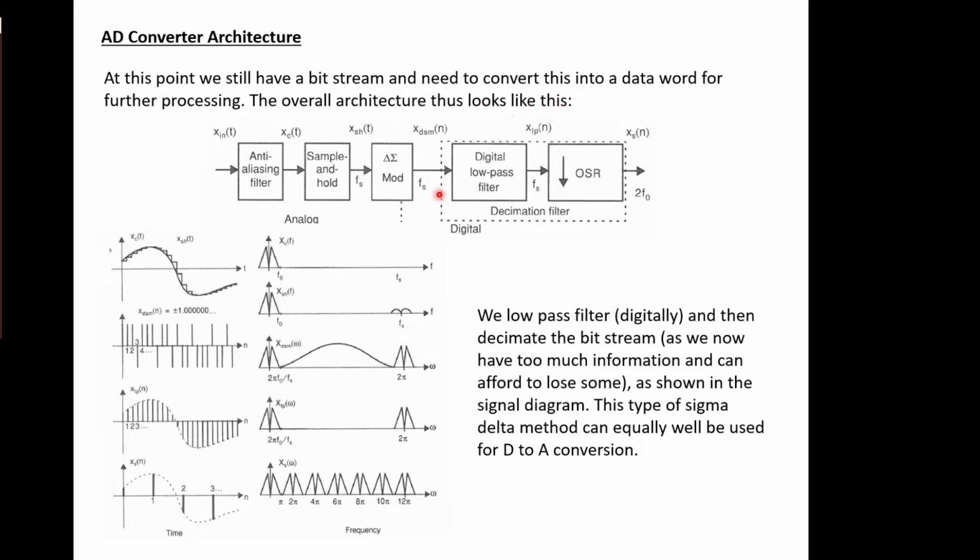So we would then feed our pulse stream into a digital low pass filter, which would take all those bits, feed them back on themselves again, and would recreate the digital signal as is shown in this graph here. So here's our modulator output whizzing through. There's the noise shaping. We then apply that to a digital filter with a cutoff frequency here that gets rid of all that noise and just allows our message to be here. And you can see that the digital amplitude of the output of the digital low pass filter, the output signal is starting to come into play.